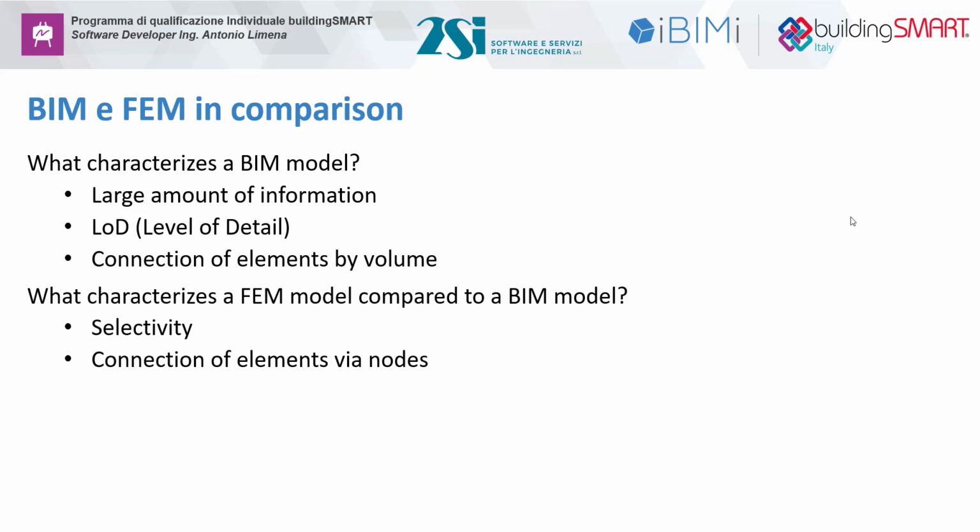Especially you have to model only structural elements. You don't have to model everything in the structure. You don't care about architectural elements and everything that is not structural, basically. Then other elements are going to be implemented in the model as loads, but not as elements themselves.